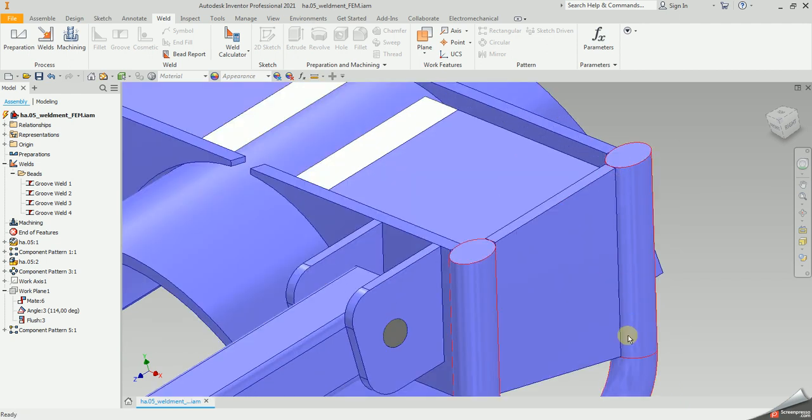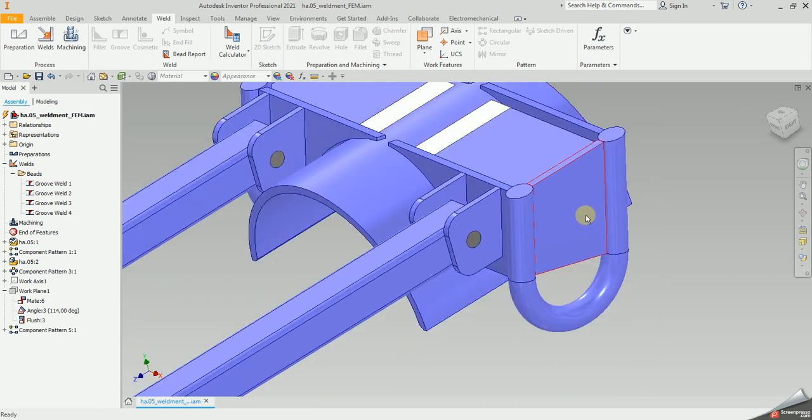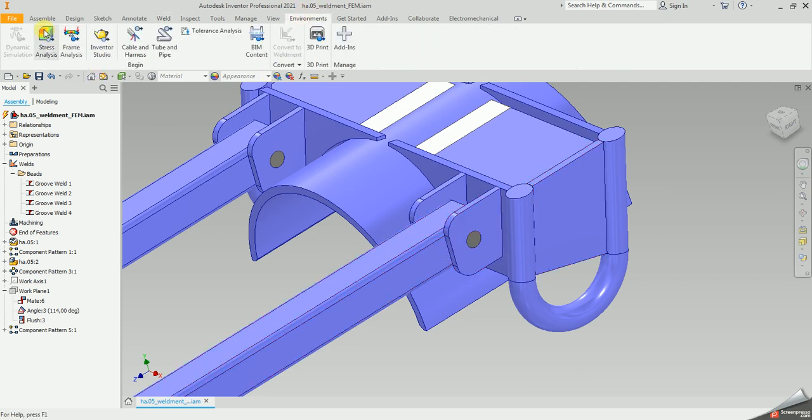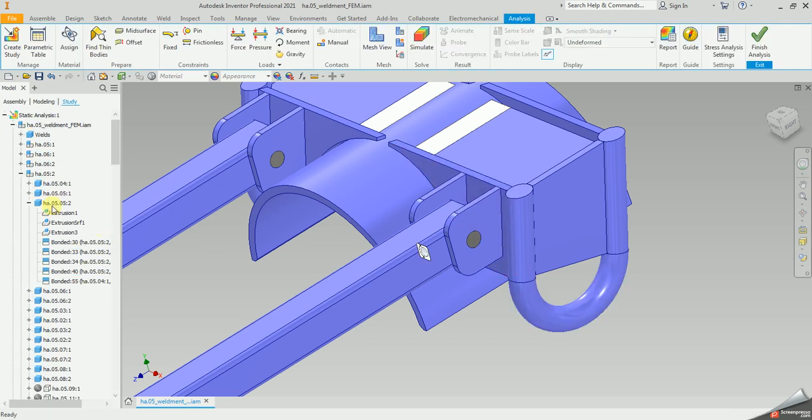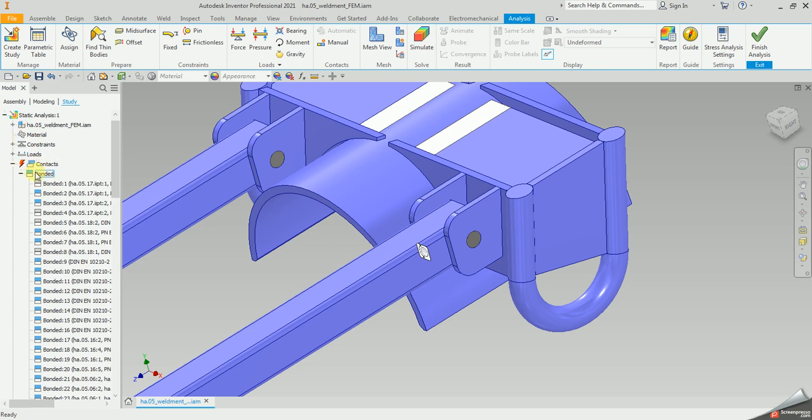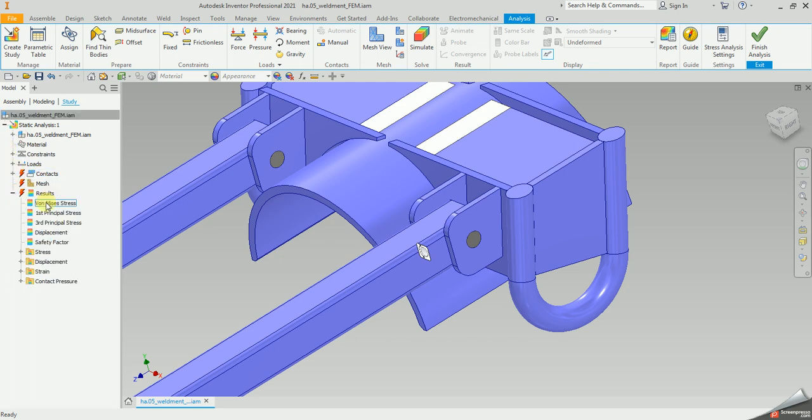Of course, in the end there are fillet welds here and also there, so actually the area of the weld is made bigger than the area of the plate itself, but as long as it is not strictly necessary to model welds, personally I try to avoid them for obvious reasons.